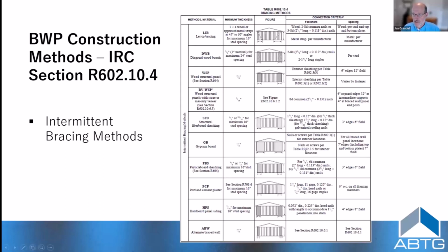How much strength do I need? The different bracing methods have different strength, and that will show up in the bracing amount that's needed. The weaker method is still a good method, and it may have advantages for other reasons. You just need to have a little more space on a wall line to do that.